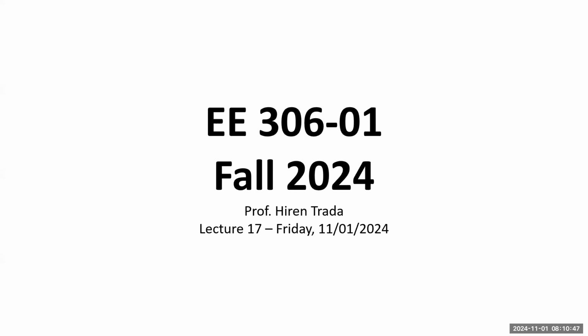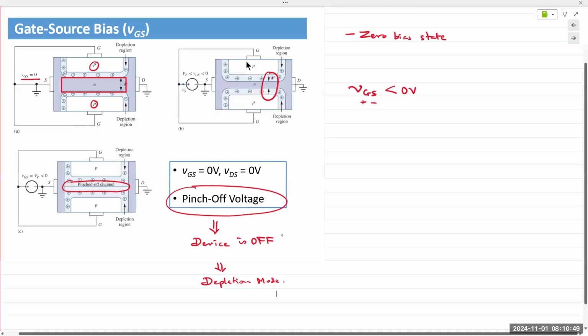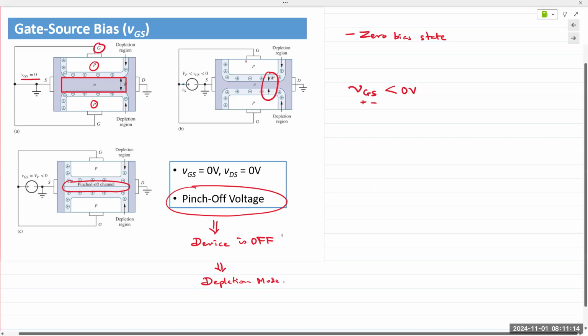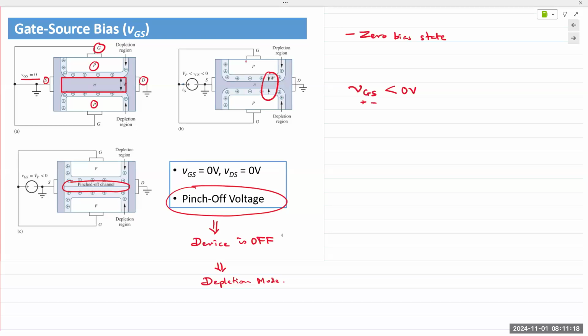Okay. All right. So just as a quick recap, we were looking at an N-channel FET that was implanted with a P-type material on both sides of the channel. By normal interaction at equilibrium between the P and N junction, we have a depletion region that is established at both ends. Both of the P-type materials are connected together into one single terminal known as the gate, and the far ends of the channel are labeled as the drain and the source.